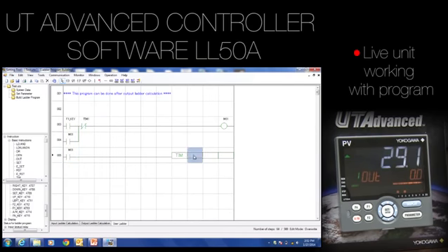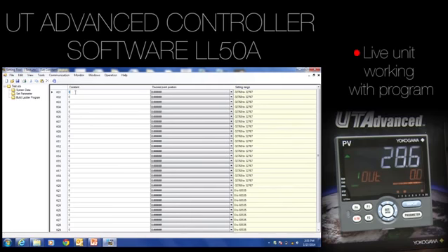Timer, we should make this a clock. We're going to make this a 1 second clock. This is going to be timer 1. And then we're going to make this a K value. Let's make this K value K01. K is a constant value, and a constant value is just some value that we can store in here to use as a variable in the menu. So K01, we're going to go to Tools and set a constant. That constant here is 0. Let's make that 10.